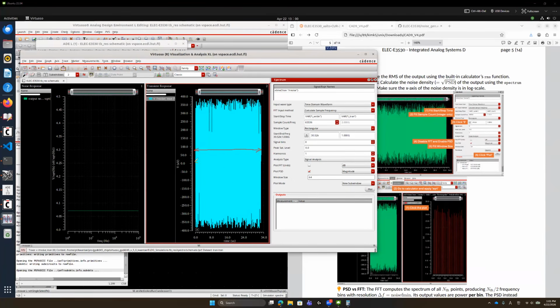we run FFT based power spectral density, and so on and so forth here. And this is 64. And previously it is 65536. So the difference is that for each learning FFT window, we are learning this amount of FFT, and then we do the averaging. FFT result, FFT result. So we do the averaging. So this kind of fluctuating, noisy output can be averaged out to less fluctuating.